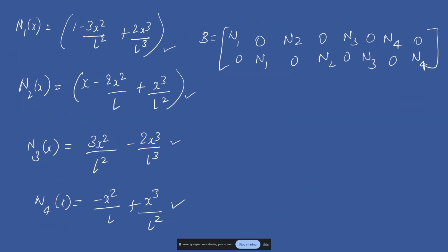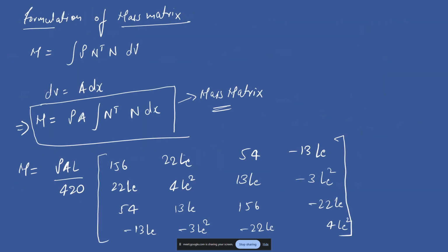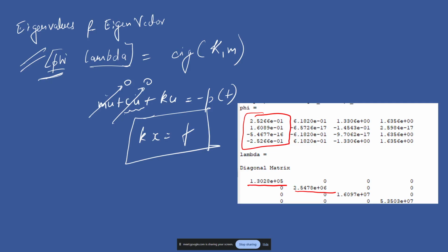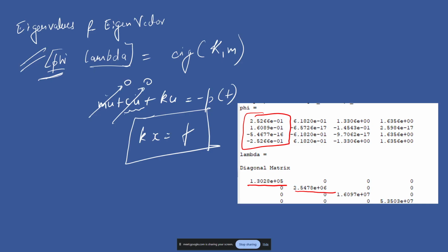Because ultimately, the stiffness matrix K global which we are having with us, we want to decompose into a lower triangular and an upper triangular matrix. Those triangular matrices we can utilize to perform the forward and the backward substitution to get the corresponding solution of the system.